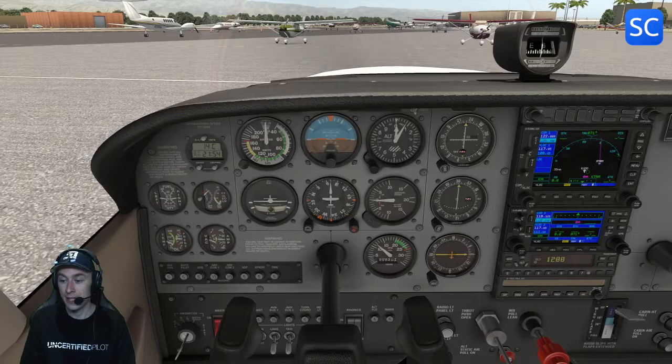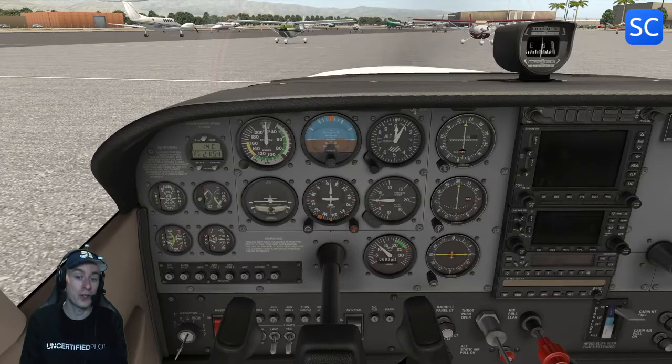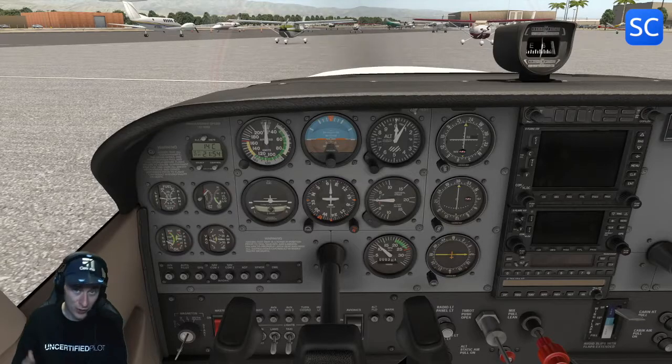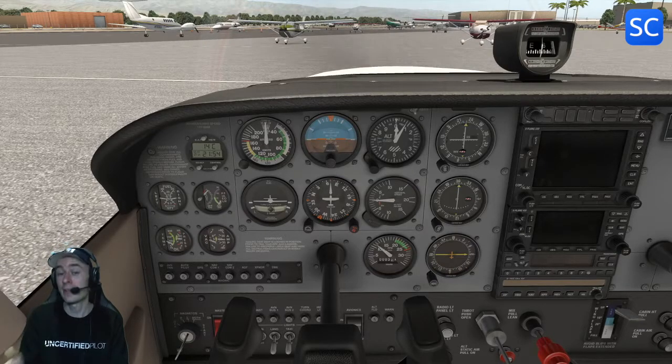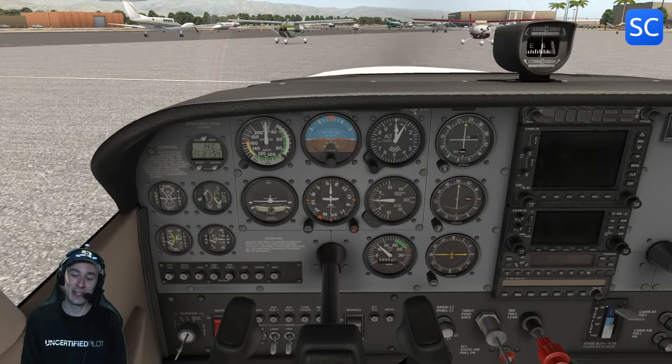So to prevent that scenario from happening, it's very important that you switch off the avionics before you shut down the engine, or switch off the avionics before you start up your engine. If you don't, with the REP, you actually run the risk of damaging your electronic system, and it will fail, and it will be kaput, which I think is really great. Again, talking about flight realism.